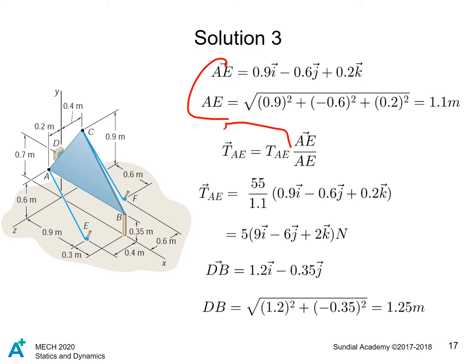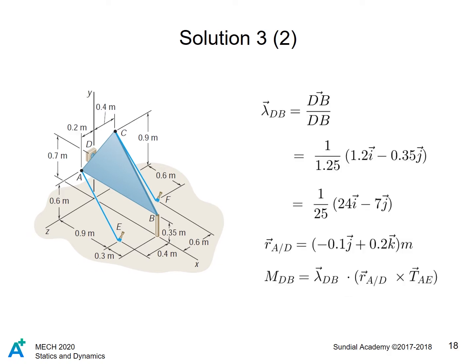We then construct the radius vector from D to B and find the cross product of the radius and force vectors. Then we must find the unit vector of the direction vector dB. Why do we do this step? We do this step so that the moment axis is taken in such a way that the results are not inflated, yet still accurately reflect the angle between the general moment axis and modified moment axis. If we recall the dot product formula of magnitude V1